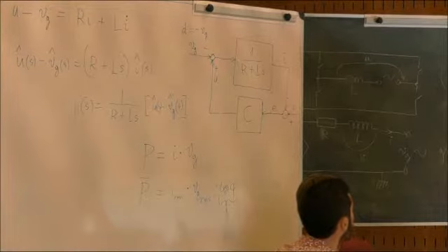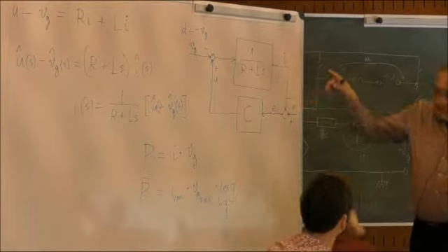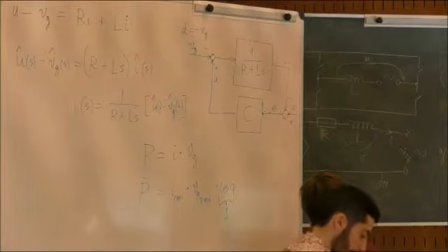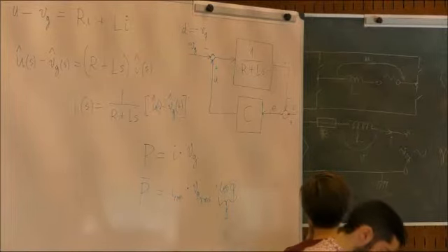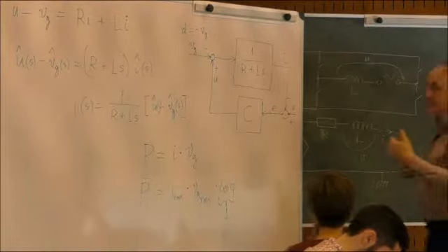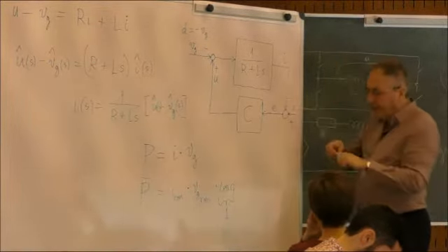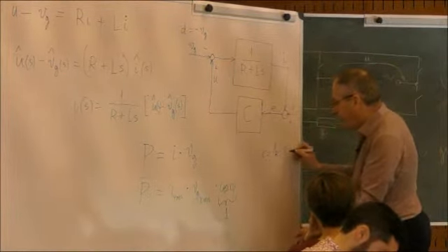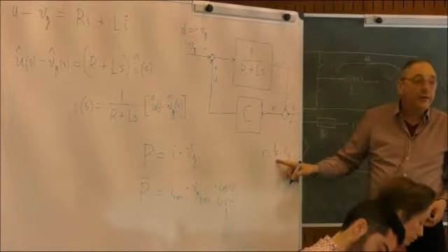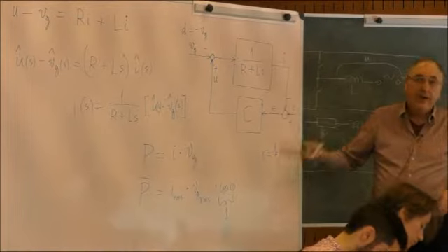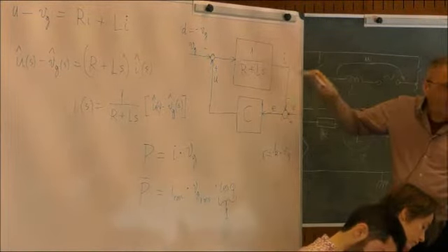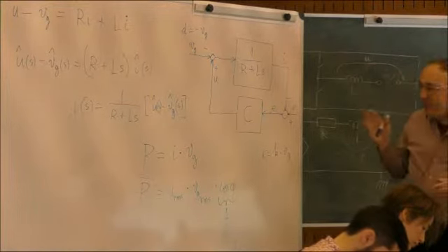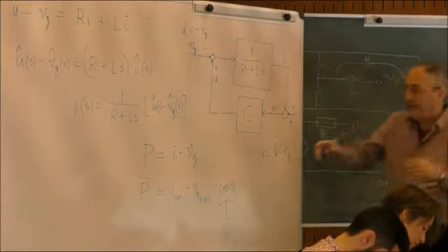So that means that there is actually another feedback loop around this system which searches for the optimal voltage, and it adjusts the power by adjusting the constant. So R is some constant K times Vg, yes? But this constant is not really a constant. It is given by another feedback loop built around this system, which adjusts K so that at the optimal value I get the highest possible power.